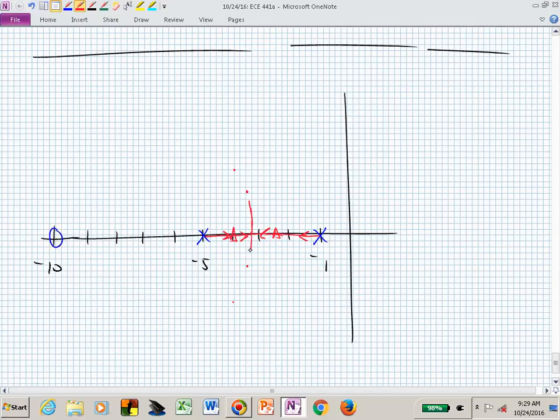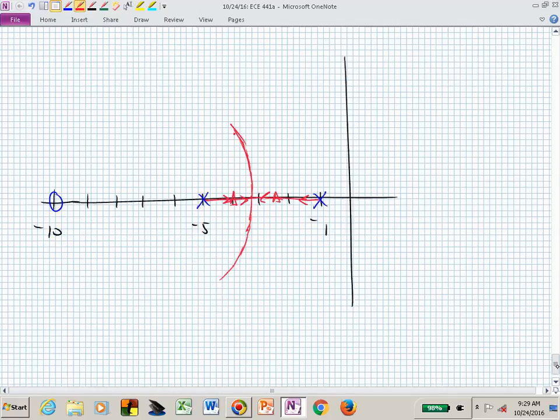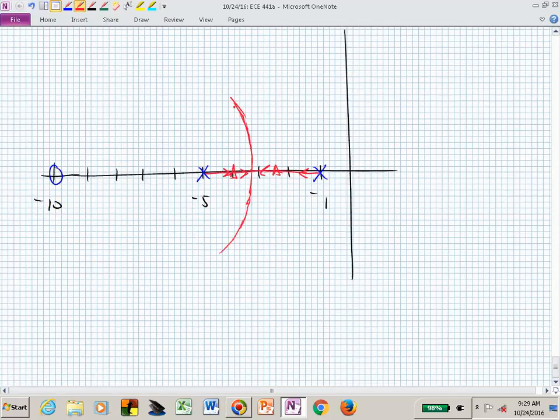And in fact, because of this particular pattern of poles and zeros, now if you actually brought your compass in, you could use it. You could put the center of your compass at minus 10. You would spread out that compass to give you a radius that was the breakaway point, and then you could just complete this circle. Isn't that beautiful? Isn't that pretty? That's our root locus pattern. And I'm going to run out of space, but now the radius is a little bit less than 7, right?